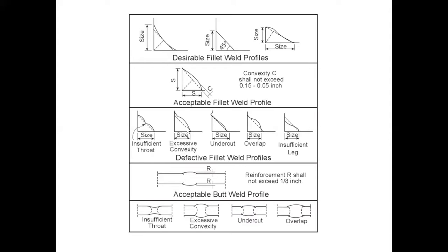Here, it looks like this person is doing a horizontal weld. Maybe got a little too hot, because we see what's happening here. Almost looks like what we see when we get undercut. We get a washout here and then a pile up at the bottom. That could be multiple factors going into that one. Long arc length often creates stuff like that because your arc is heating up a bigger area, and then it heats up more of the material. It falls down and doesn't replace all the material that it cuts down.